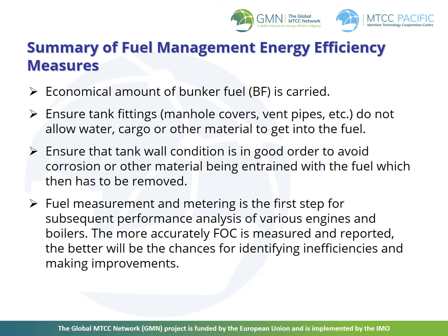Monitor fuel oil sludge levels and ensure that sludge levels are not high due to poor maintenance of the purifiers. As advocated, homogenizers can be used to reduce the sludge levels. Fuel measurement and metering is the first step for subsequent performance analysis of various engines and boilers. The more accurately that fuel consumption is measured and reported, the greater will be the chances for identifying inefficiencies and making improvements.